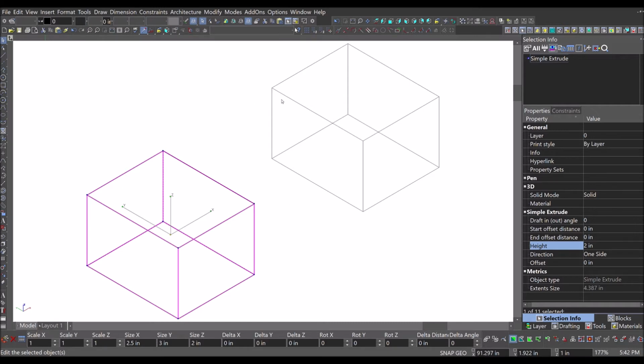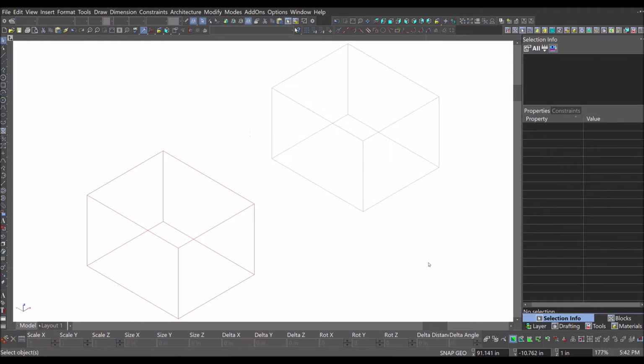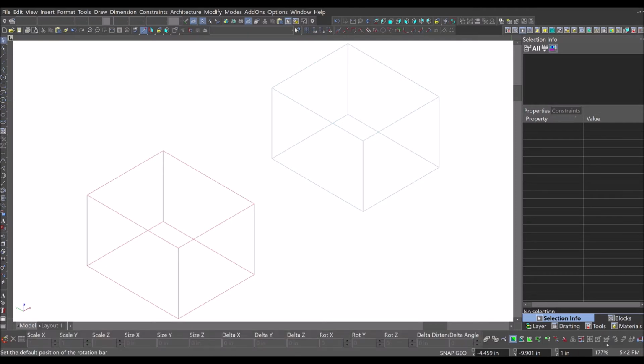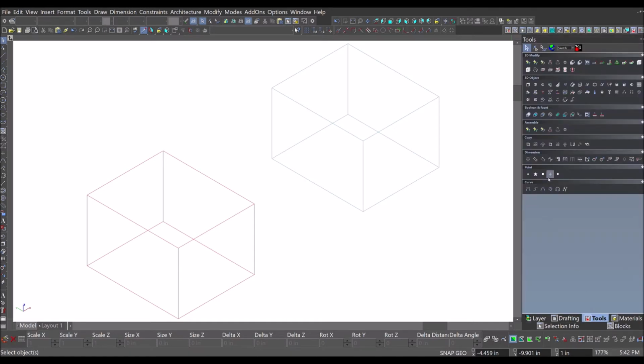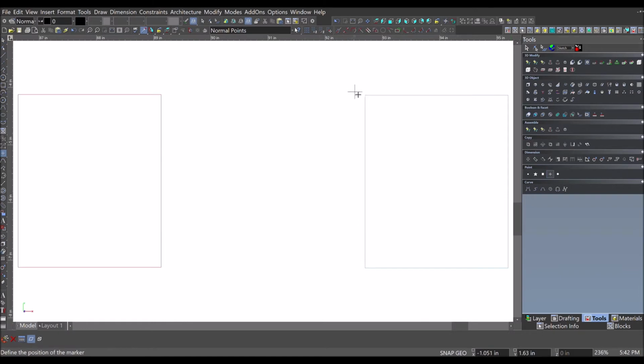Both cubes at this point should be identical. On the x-axis they should be 2.5 inches, on the y-axis 3 inches, and on the z-axis 2 inches. And in a minute here I'm going to do a radius of 0.060 on the edges, and then we're going to drop some tapped holes in it for some bolts. Well, I said that wrong. Actually, I'm going to do the tapped holes first because I want to have a nice corner edge to work from.